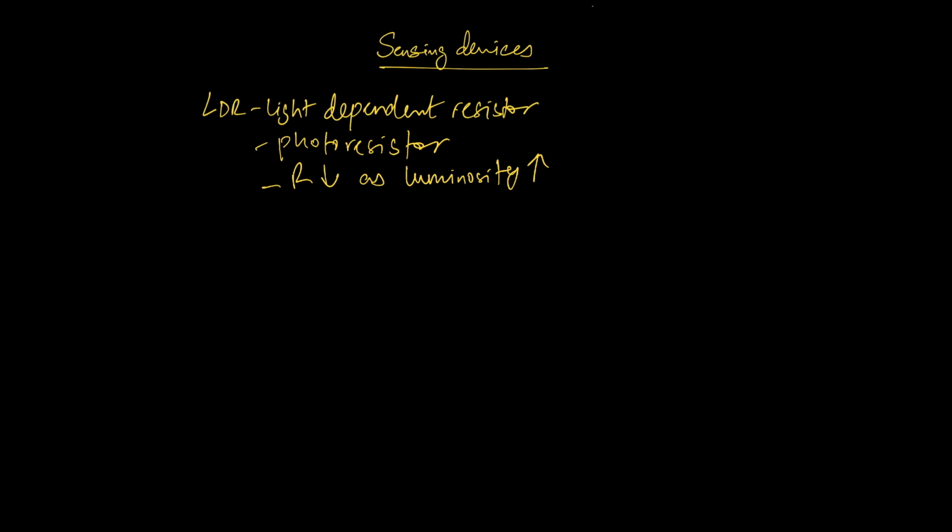So you can have a photoresistor in light-sensitive detector circuits, or in light-activated or dark-activated switching circuits. In the dark, the photoresistor can have a resistance as high as several mega ohms, and in the light, you can have a few hundred ohms of resistance. In essence, if incident light on a photoresistor exceeds a certain frequency, the photons are absorbed by the semiconductor, and they give bound electrons enough energy to jump into the conduction band. Basically, it generates free electrons.